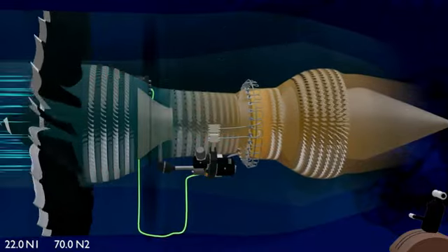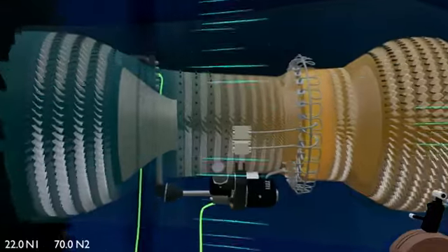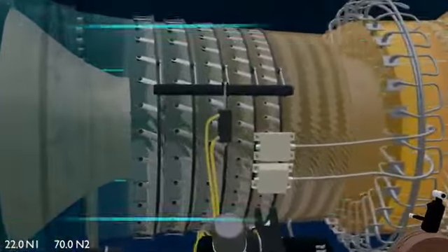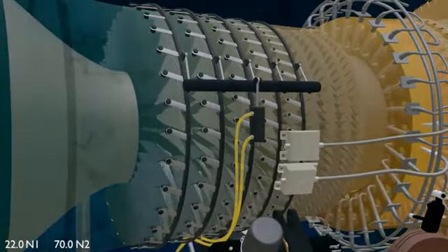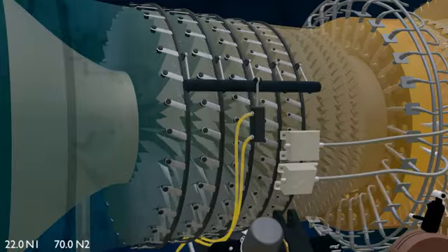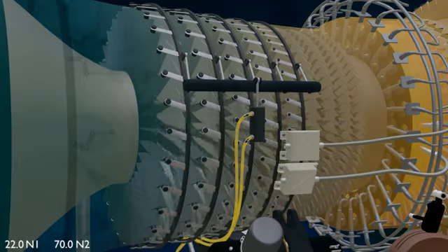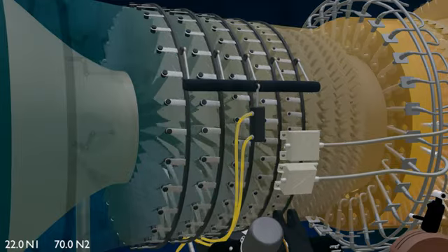To prevent this, the EEC commands the HMU to operate the variable stator vane. The HMU now sends pressurized fuel to the VSV actuators. Two VSV actuators on either side of the engine control the torsion rods. The torsion rods are connected to 5 unison rings on the HPC casing. The unison rings with linkages turn the IGV and stator vanes of the HPC stages,